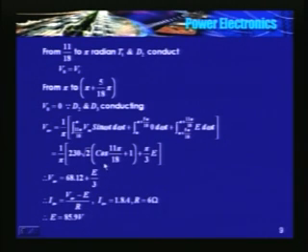I got an average value in terms of E. Now I average is V average minus E divided by R. So the value of I average is 1.8 amperes, R is 6 ohms, these are the two parameters given. So E is 85.9 volts.